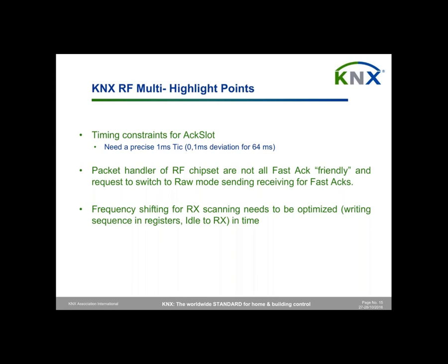The third issue you may have, to be worked in detail, is the frequency shifting for RX scanning. Not to write all registers always, but only to write what is needed, because writing a register takes an amount of time requested from the chip. Also remember that when you change registers, the chip sometimes needs to go from idle to RX, PLL synchronization or other things. And this time must also be less than 1 millisecond.